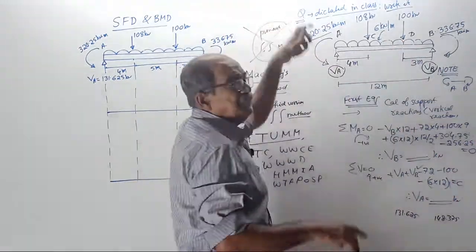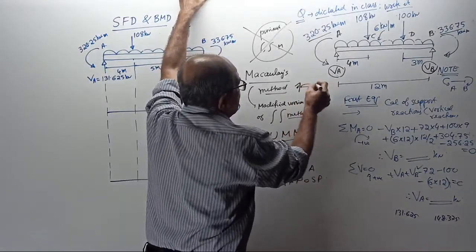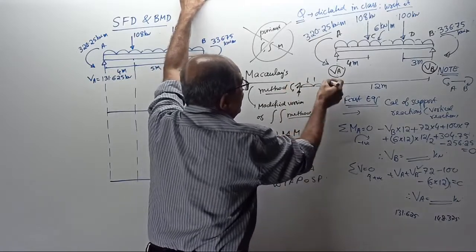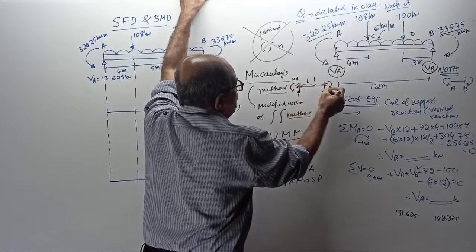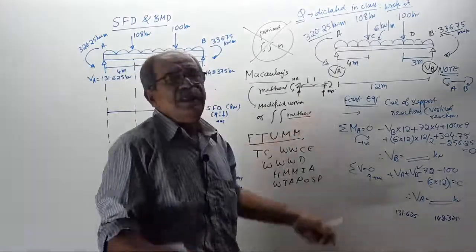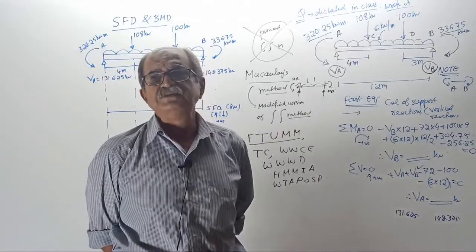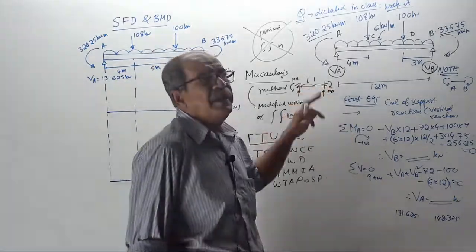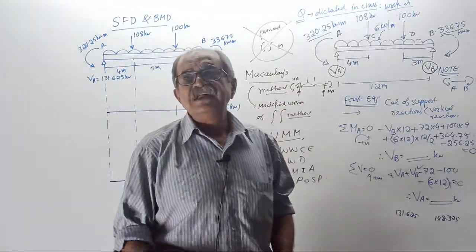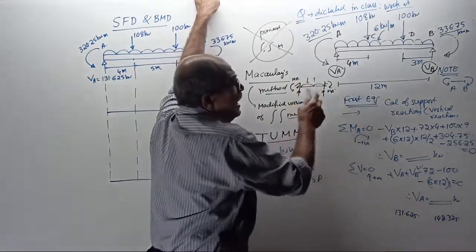If the beam is a fixed beam, both A and B are fixed, then there is a vertical reaction, and reacting moments MA and MB. So there are 4 unknown reactions, and only 2 equilibrium conditions, sigma M equal to 0, sigma V equal to 0; sigma H is not used. This is statically indeterminate to the second degree. So you should analyze this fixed beam and reduce the indeterminate state to a determinate state. I took MA and MB as redundants.